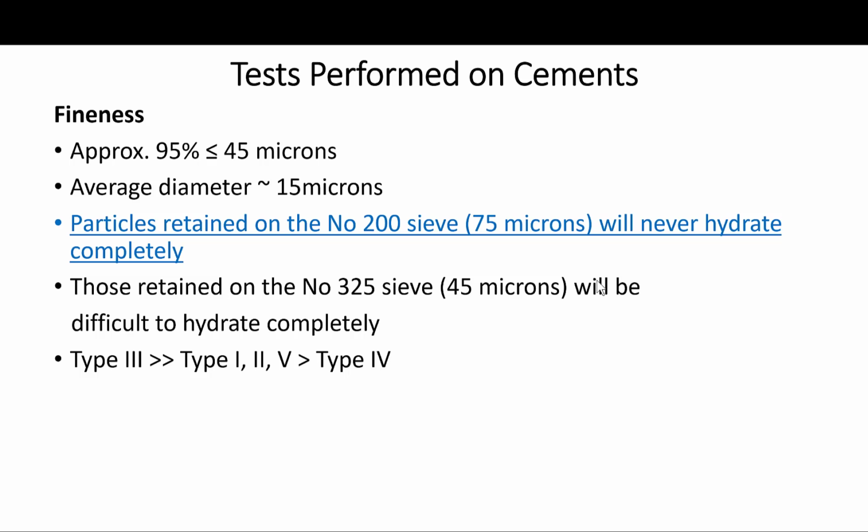So it must be noted that, for the irregularly shaped cement particles, no two methods of measuring specific surface will give the same results. This is partly because the different methods tend to measure somewhat different properties, and partly because of the assumptions required to develop mathematical relationships for the calculations.